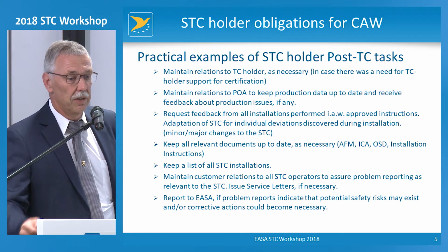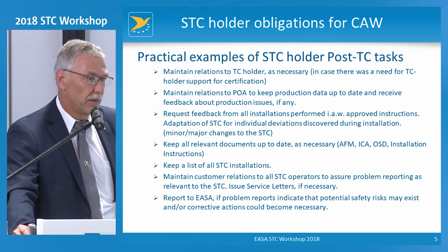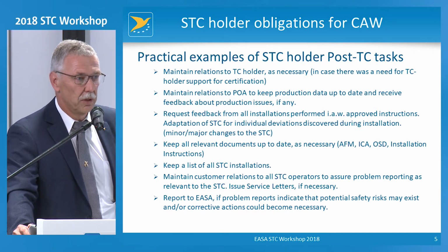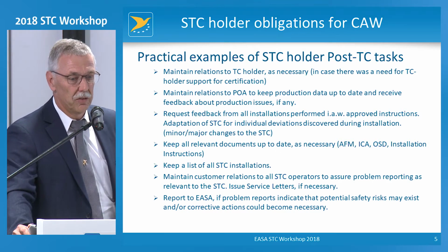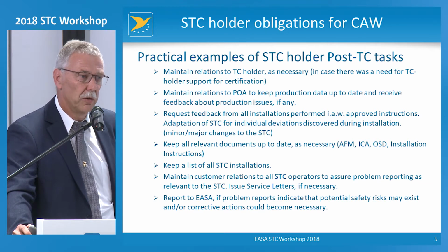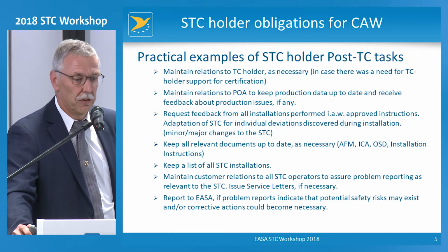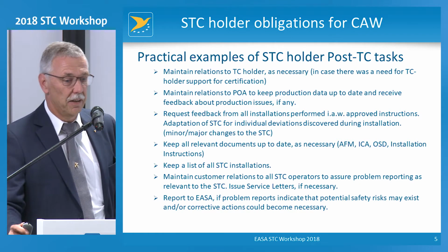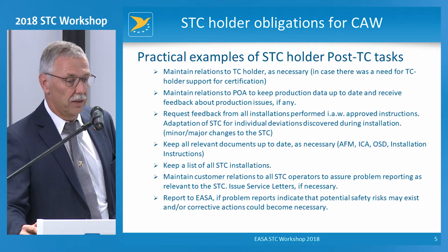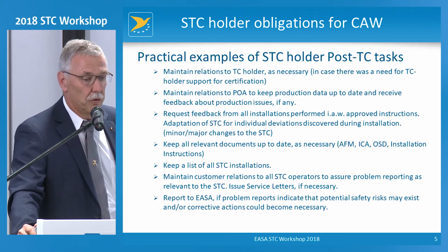Then you also have to maintain relations to the PUA and probably the maintenance organizations that were installing your STC. If it's multiple installations, you have to know whether there were difficulties during the installation. Probably you had to have minor changes to adapt your STC for the specific aircraft, because not all airplanes are the same. And that's why I said you should request feedback from all the installations performed with the approved instructions.